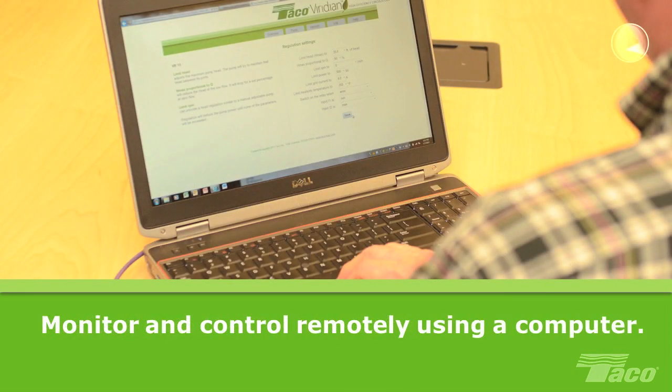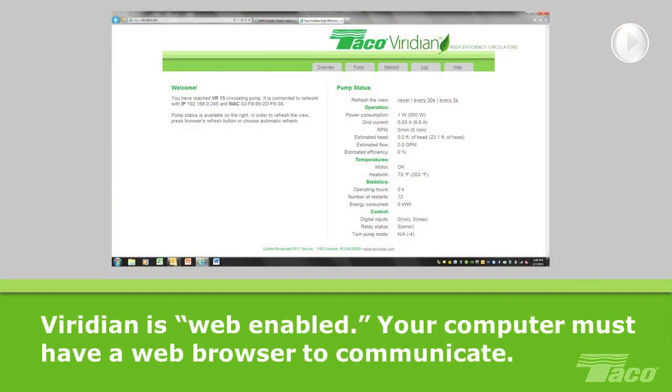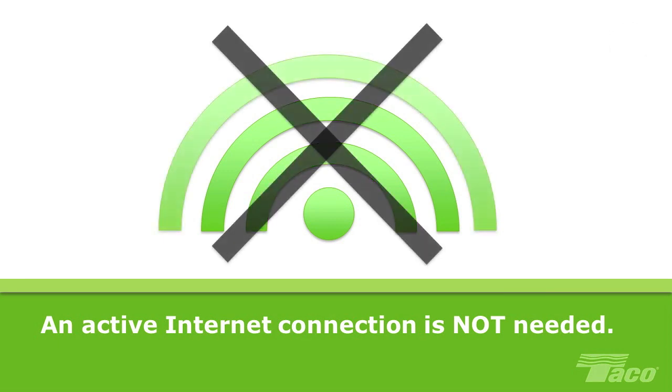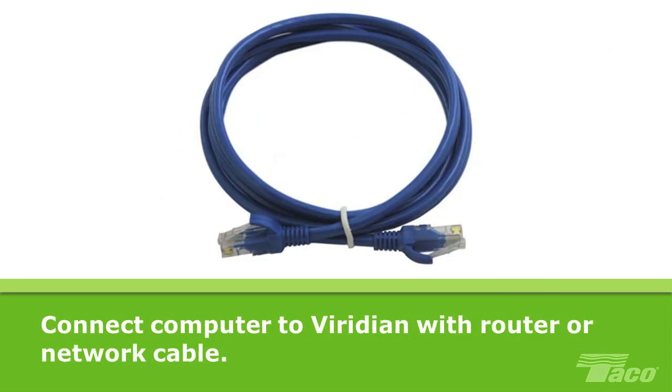Viridian status can be monitored and operations controlled remotely using a personal computer or laptop. Viridian is web-enabled, which means you communicate with Viridian through a web browser. Therefore, your computer must have an internet browser installed, such as Chrome, Firefox, Safari, Internet Explorer, or similar browser. But an active internet connection is not required. The computer must also be connected to the Viridian either directly using an Ethernet crossover cable or connected via Ethernet cable and a router to a computer network, LAN.